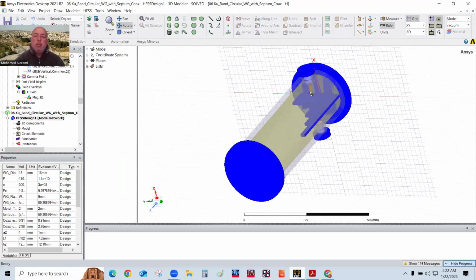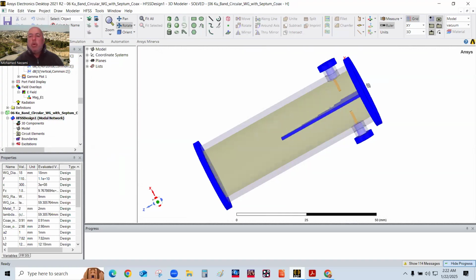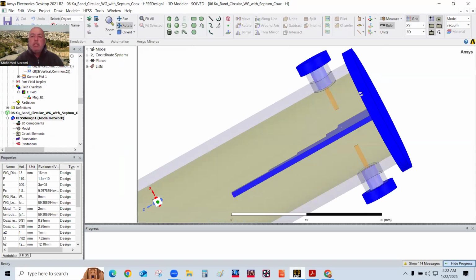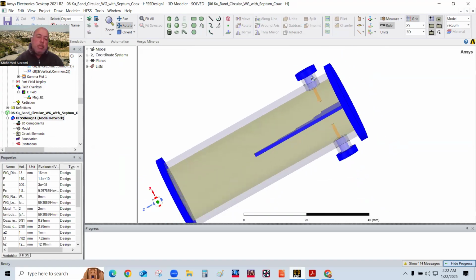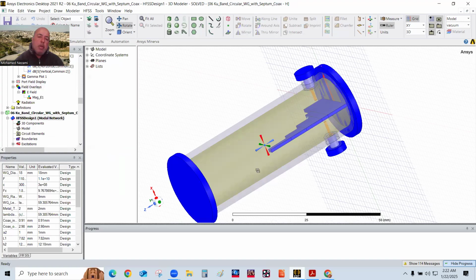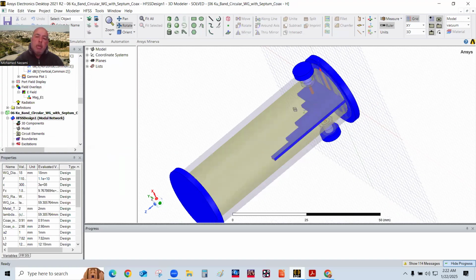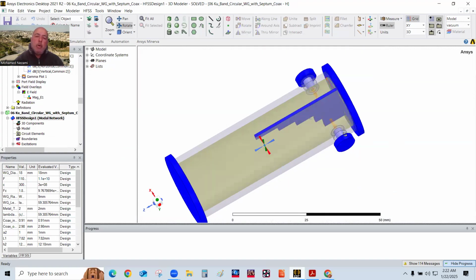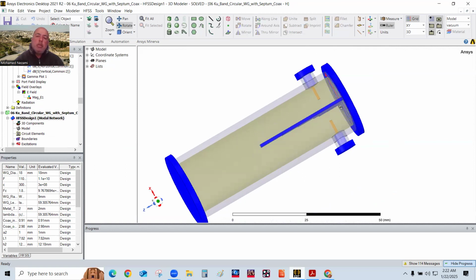You can see the probes in here, even though these are wire probes, the same applies. The wave comes in, a circularly polarized signal from here, propagates through the septum, and gets separated into two parts. For the placement of these probes, they have to have a back end that is a quarter wavelength distance from the center of the probe so that the probe doesn't see any loading.